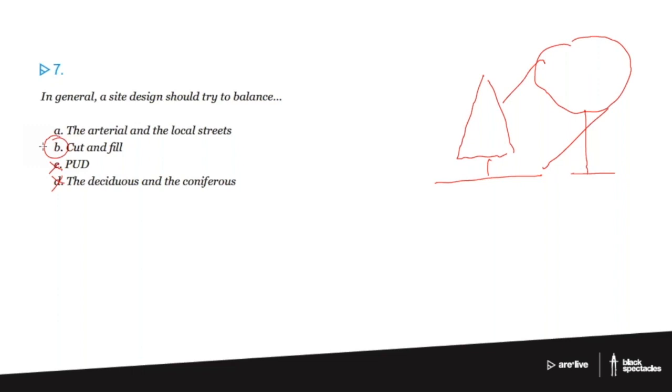Well, cut and fill is the idea that if I'm being a smart designer and I decide that we're going to dig out, we're going to excavate a bunch of the site in order to do a basement and to do some bioswales and to move the water around in a particular way, I'm going to dig a bunch of soil out. I can either take that soil and put it in a bunch of trucks and truck it somewhere at massive expense because soil is heavy and the trucks are expensive, or as a smart designer, I can say, well, wouldn't it be smart if I dig out some over here, maybe I make a mound over there. And that's the idea of balancing cut and fill.